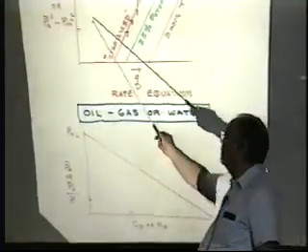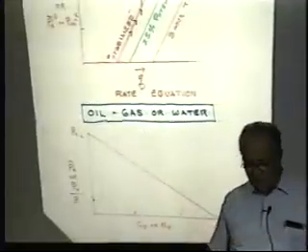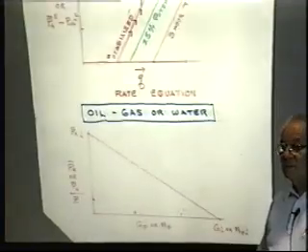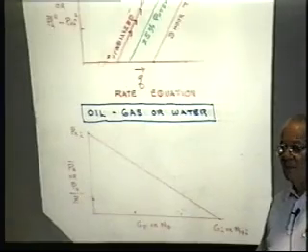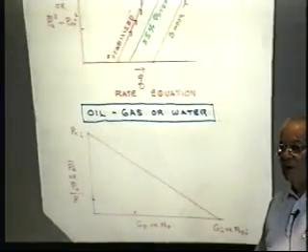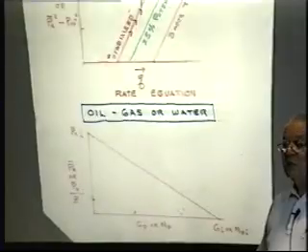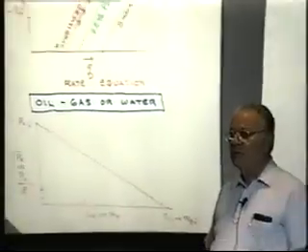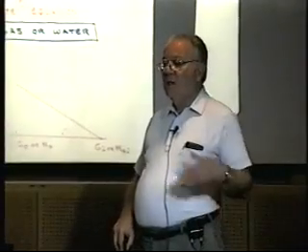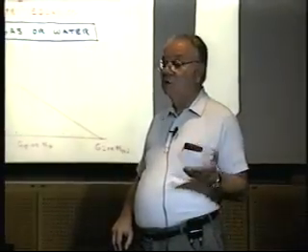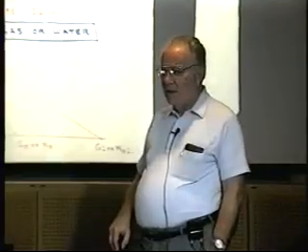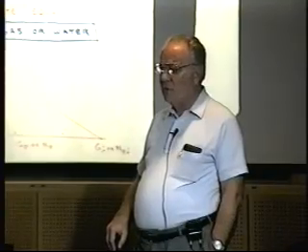We've demonstrated with our isochronal testing of oil wells that for your solution gas drive reservoir performance, that behavior down in that region is a function of a difference in pressure squared. Above the bubble point, it would be delta P. Single phase water flow would be delta P. A lot of people use inflow; there are a lot of programs out there that use Vogel's equation for inflow performance. And several also use Vogel's equation for water flow.